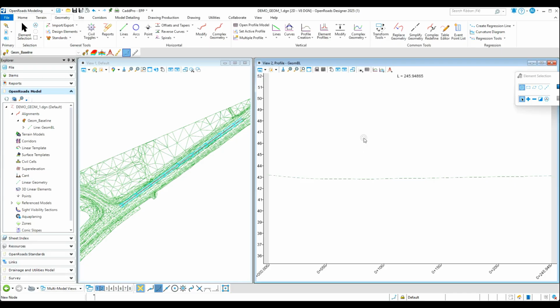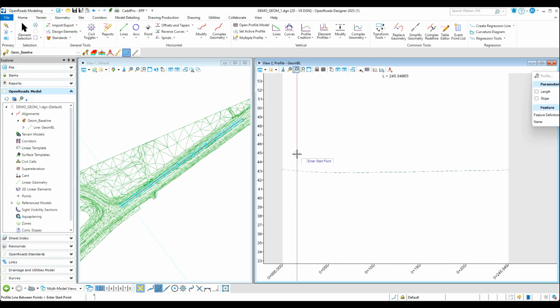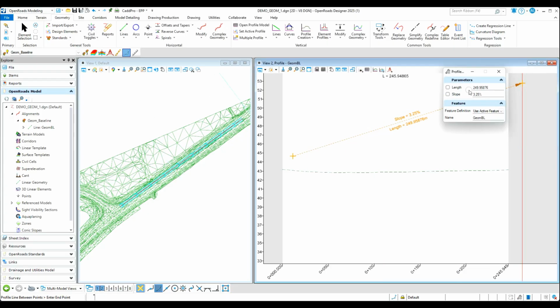Okay. Tip number 2 is to place lines at a distance and slope. So we'll just place a line, and we've got two choices here. We can either lock on the length here as 100, or we'll make it 1%, and we've got a vertical line.